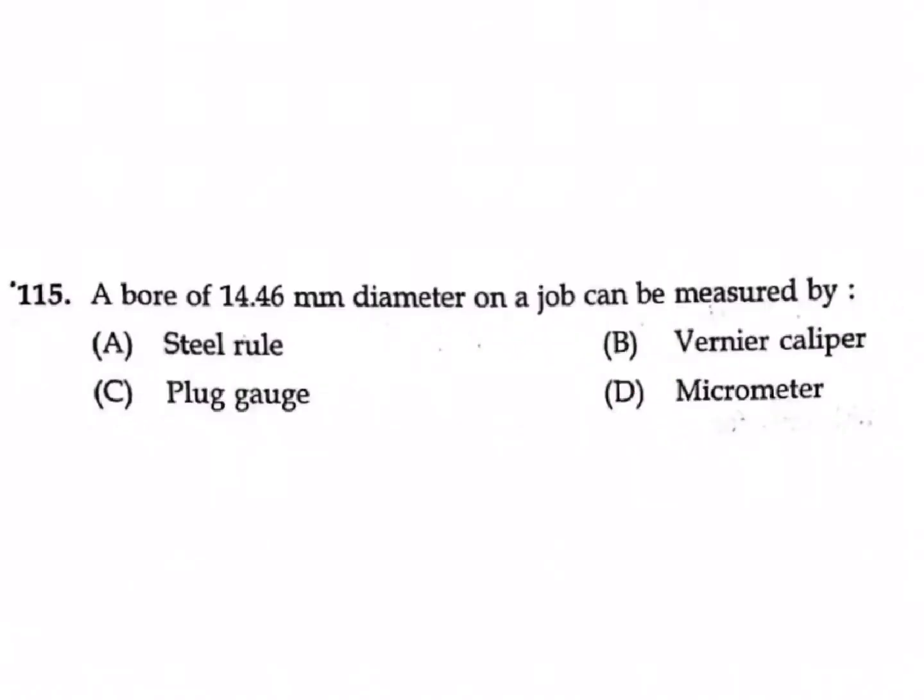A bore of 14.46 mm diameter on a job can be measured by steel rule, not require. Plug gauge also its measurement, so plug gauge not require. Then either vernier caliper or micrometer. Micrometer generally external dimension. It's bore, so micrometer also not possible. Only option B, vernier caliper.